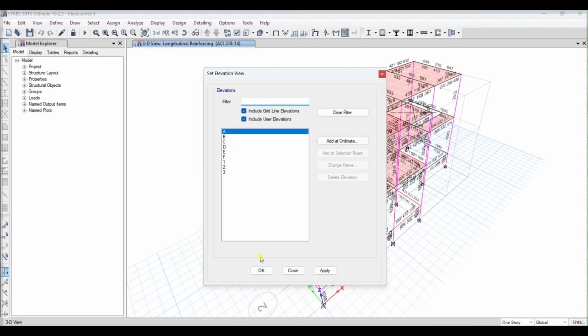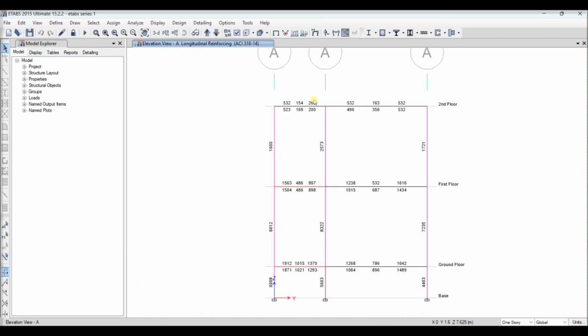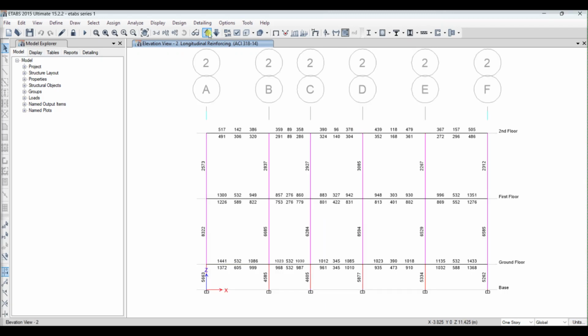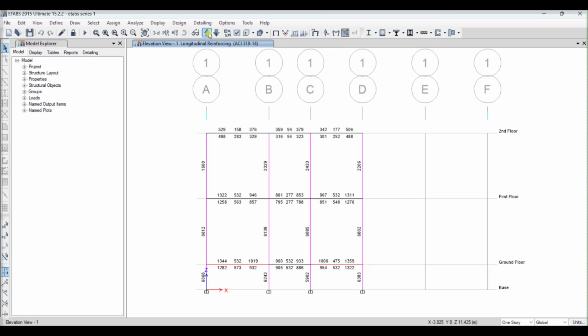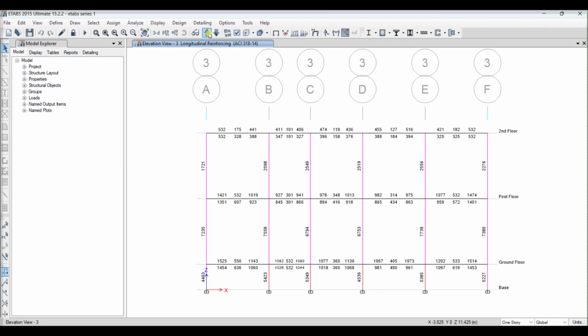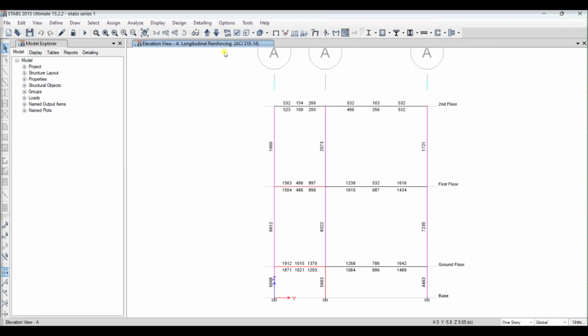Okay, so here maybe you can check by the elevation to whether your some column are under stress or not. By using this move up list, here you see no member is under stress. Okay, some red lines are there but no member is under stress. So almost your column, your frame structure is passed.